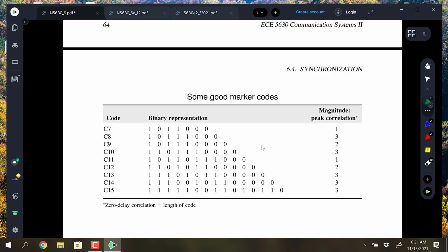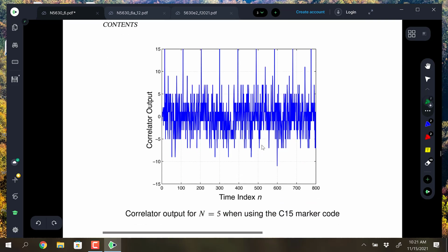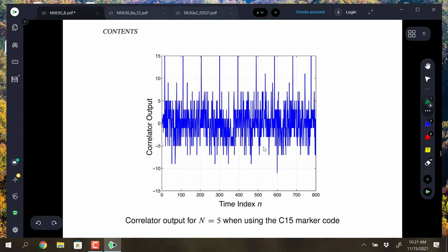It's done as a digital correlator, and then you can find where it starts. So I attempted to write something in M code, playing around with them, but I don't want to talk about it because I'm not really that knowledgeable of it. It is what it is, though. It's some short-length code that's good at having low cross-correlation. That's the really main thing about any sync code. It's going to be possible to have any sync code you create appear in nature as a random bit pattern, and that will confuse the ability to sync.